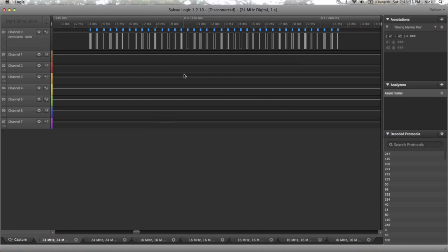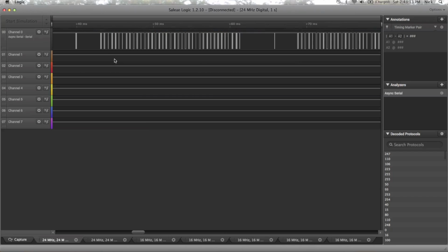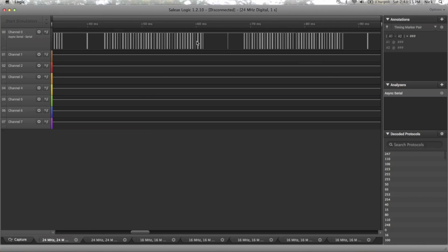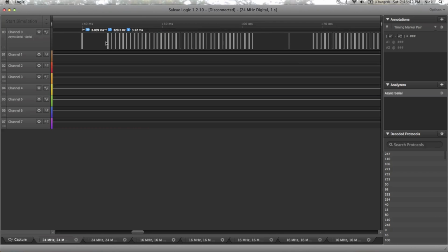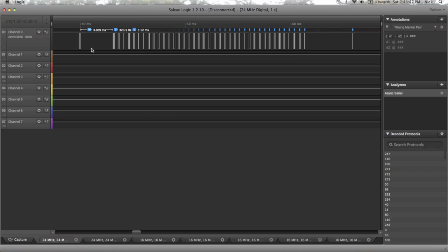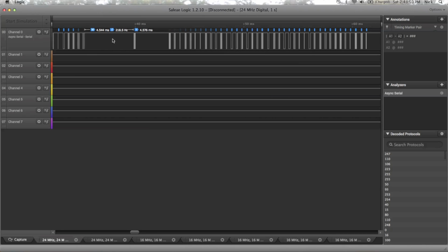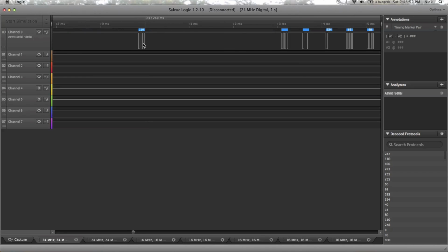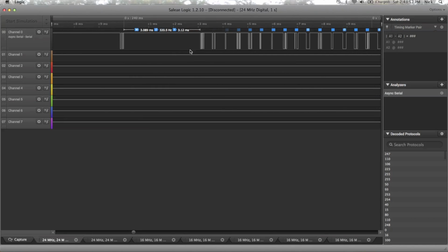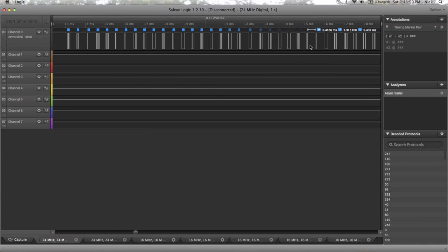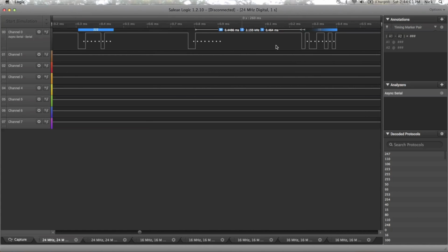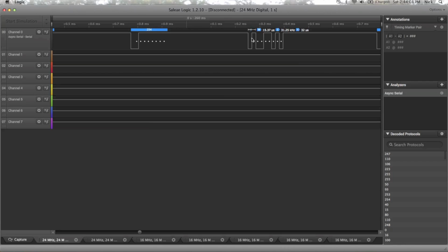And then when it's on, things get a little more interesting. Now, at first, I thought that each one of these was an entire stream, but that's not the case. It's only most of the stream, or a little bit of the stream, and then a little bit more. So it's not perfect. Sometimes it's 35, sometimes it's 36. It's a little random. But the pattern's always kind of the same. You got a gap, and then you got a byte, whatever that byte might be. And then we got another gap, and then we have a whole bunch of them all in a row, and so forth. But it's still the same technical speed. There's just smaller gaps between each byte.